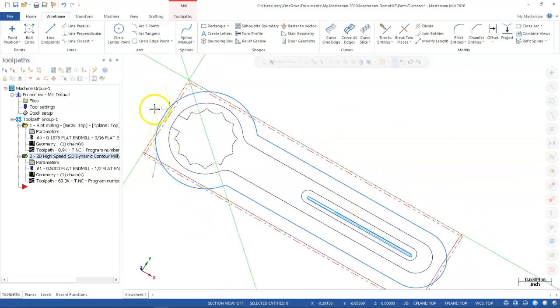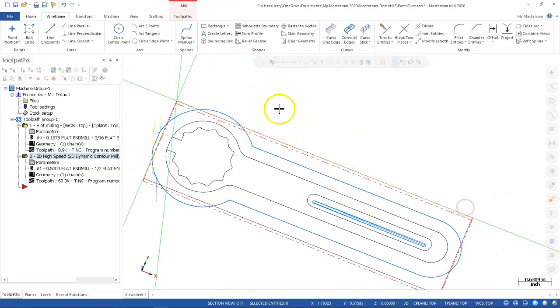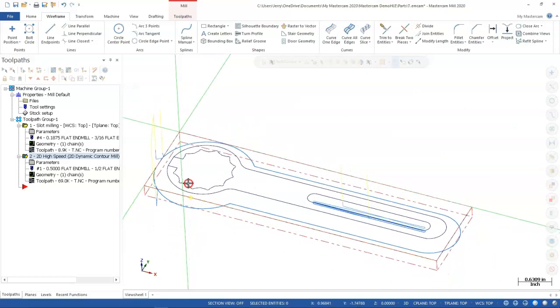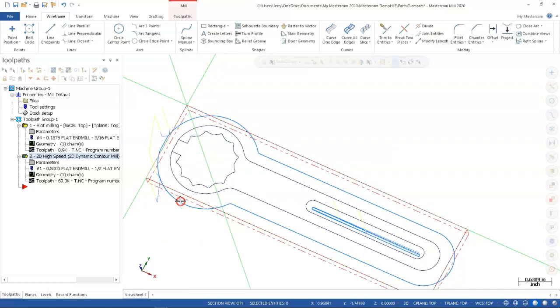So not a lot of material for it to remove, but it follows it all the way around, takes the step. So I was kind of expecting to see all those little nibble moves to remove, but at high speed, it's right there. There's not a lot of material, so even though that is not what I expected, it's not really that surprising either. It'll make the pass, come back. So it is pretty aggressive going through here, removing all of that material.